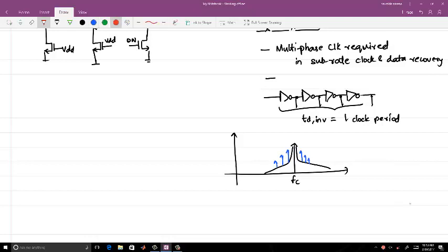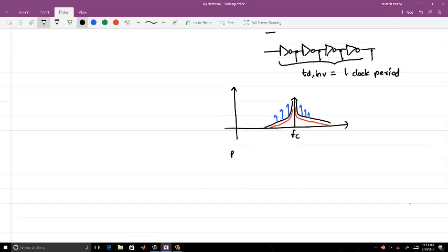And I can have a lower phase noise, let me just say, but more tones. This is one case. The other case might be that I have a higher phase noise and fewer tones. So consider both cases for RF and broadband applications. For RF applications, your spurious tones can down convert your signals. I'm talking of the receiver right now.